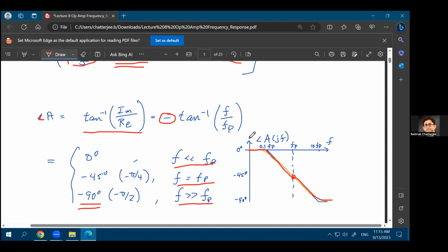Is that determined just by the individual op-amp frequency? Yes. So an op-amp. So if you look into the data sheet, that op-amp will show how much input capacitance it has, and that will be your parasitic C0. Now that parasitic C0 can vary. Even if they mention that okay, the parasitic is only 1 picofarad or 2 picofarad, that will be the ballpark range of what you will see in the data sheet.